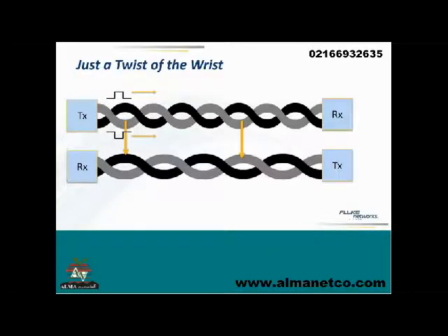They just twist the cable. So what that does is that means that sometimes the black one of the transmit pair is closer to the black one of the receive pair, but sometimes it's closer to the gray one, and over the distance of the cable, it all cancels out, and you get very, very little crosstalk. And you'll notice, if you look at this picture, hey, the one at the top is twisted slightly different than the one at the bottom. Well, in fact, that's intentional.